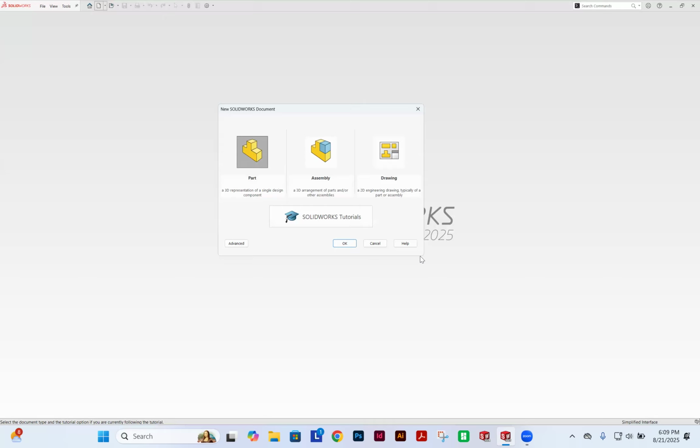instead of building a bunch of individual part files separately and then hoping they all fit together in an assembly. You should just go ahead and build them as one big part file and then split out the parts that you need if you actually need to create an assembly file based off of those. So that's what we did last semester. Just a quick refresher. I'm not going to bring up any of the files. And then, some drawings and things like that that went along with that.